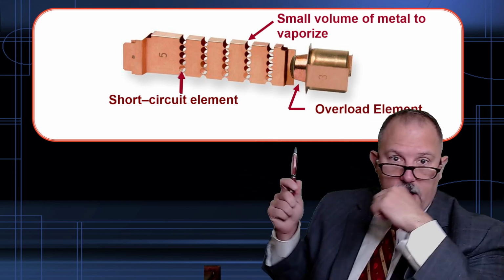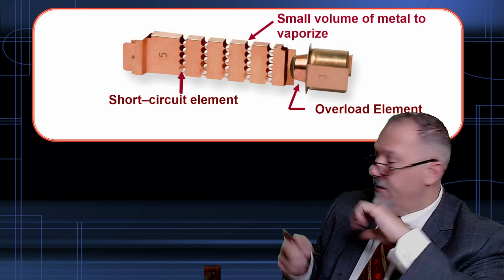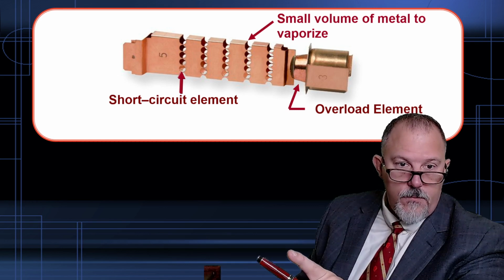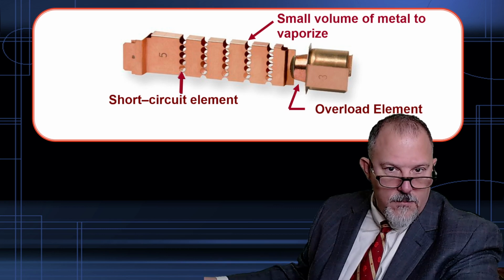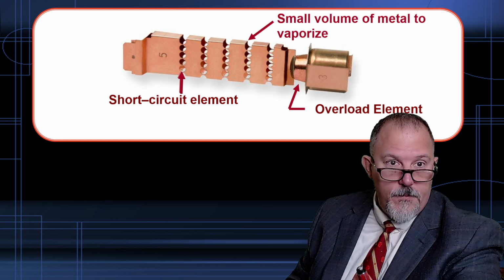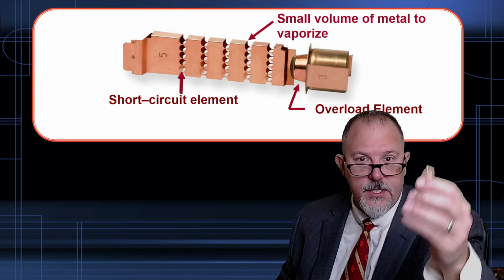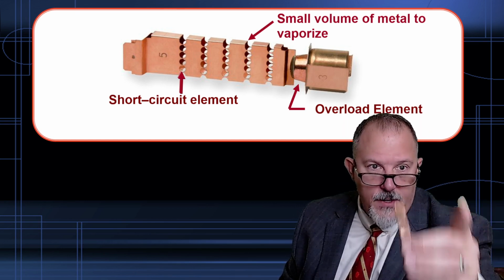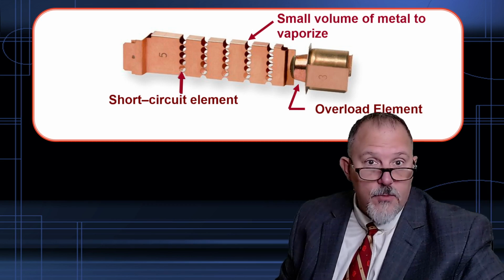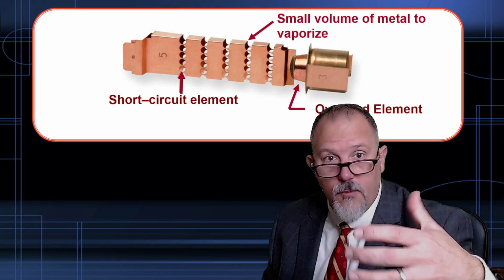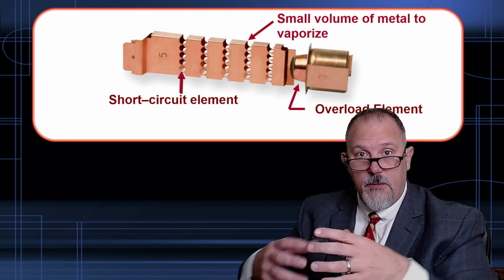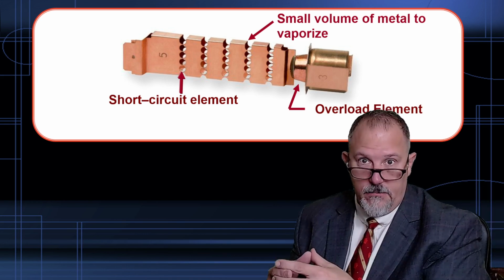Now, this overload element that's right here above my head handles the overload, and then the pinch points in the meat of the long rectangular portion of this element is what handles the short circuit currents. Now you got to remember, what I'm not showing is that this element is completely surrounded with sand.